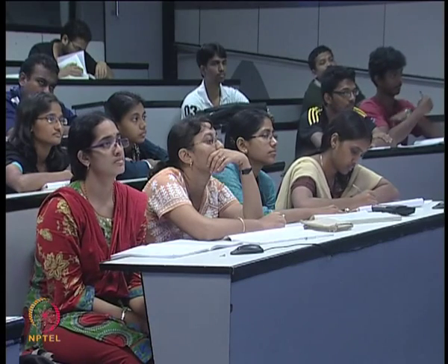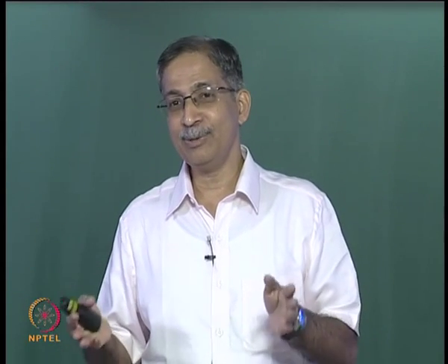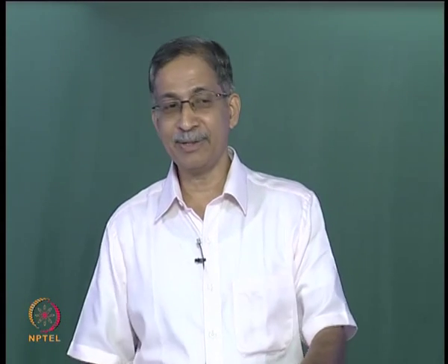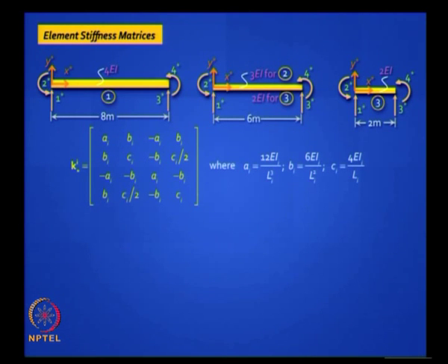Because we are doing superposition, we are taking a primary structure, putting the distributed loads, and we are adding this loading to that structure. So in the primary structure there are no displacements, d1, d2, d3, d4, d5 are 0. So that is why this must be giving you the final displacement. Is it clear? But you are right, we also have to add the indirect loads, which we will in the formulation.